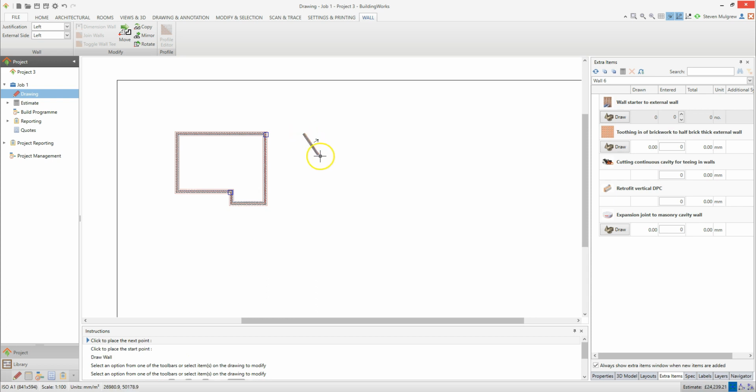If you look at the bottom right hand corner of the screen, you'll notice that the Snap button has appeared, telling us that we're in Snap mode. Snap mode is a way of interacting with your drawing. It allows you to click on points on your drawing, such as end points, intersection points and perpendicular points. The XY coordinate button has also appeared.